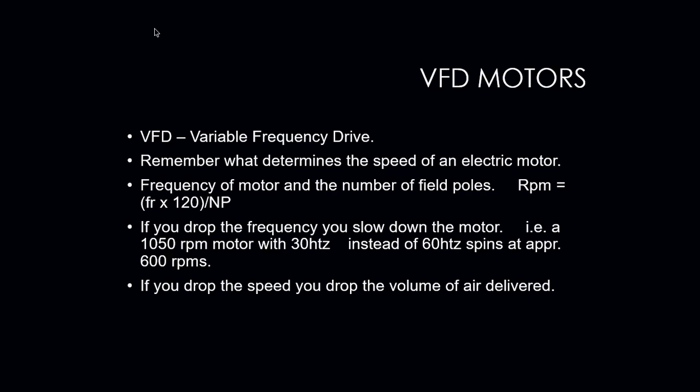Okay, and if we drop the speed on a motor, remember we are also slowing down the volume of air being delivered. And as we slow down the volume of air being delivered, we are going to change that temperature difference between our return and our supply air. So it's always important to take supply readings and return air readings, and subtract the two to come up with a temperature difference or a temperature rise.